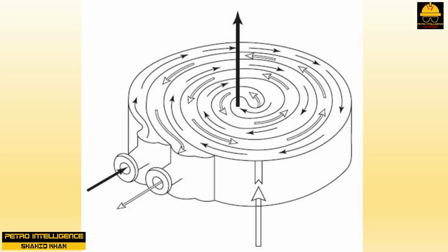Each channel is welded closed at alternate sides, shown in the picture. Covers are then bolted over each side of the spiral body to complete the unit. When both of these covers are removed, the entire surface area of the exchanger is available for manual cleaning.